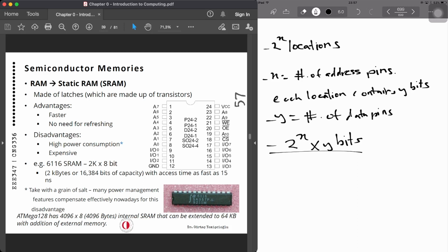We also have a chip select. These are all active low signals. The chip select is used to select the memory chip because you might have different memories in there and you can select one of those. And the IOs, as you can see, are in and out, with 8-bit data lines given the organization over there. So address, inputs and outputs.